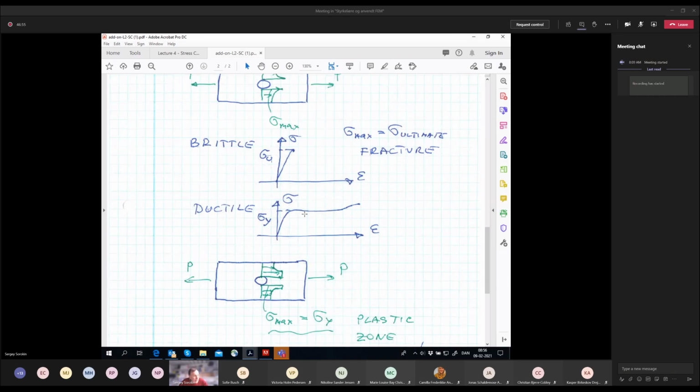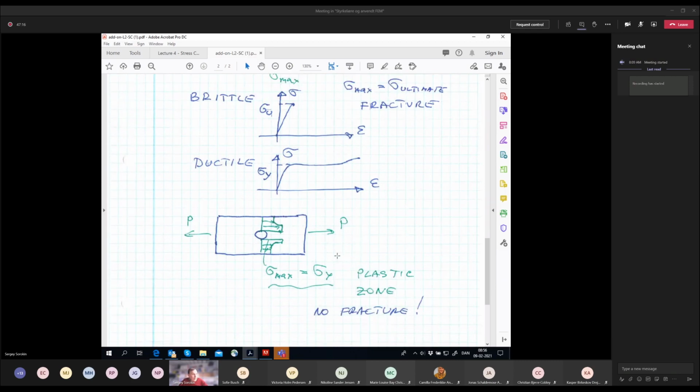So what happens is, in some cases, it's what is called a plastic hinge. If you keep on pushing with the force, the end result, which I just didn't show here but you can easily imagine, will be a uniform distribution of yield stresses here and a uniform distribution of yield stresses here, right? And this is a definite value of the force. So now let's see what's going to happen.